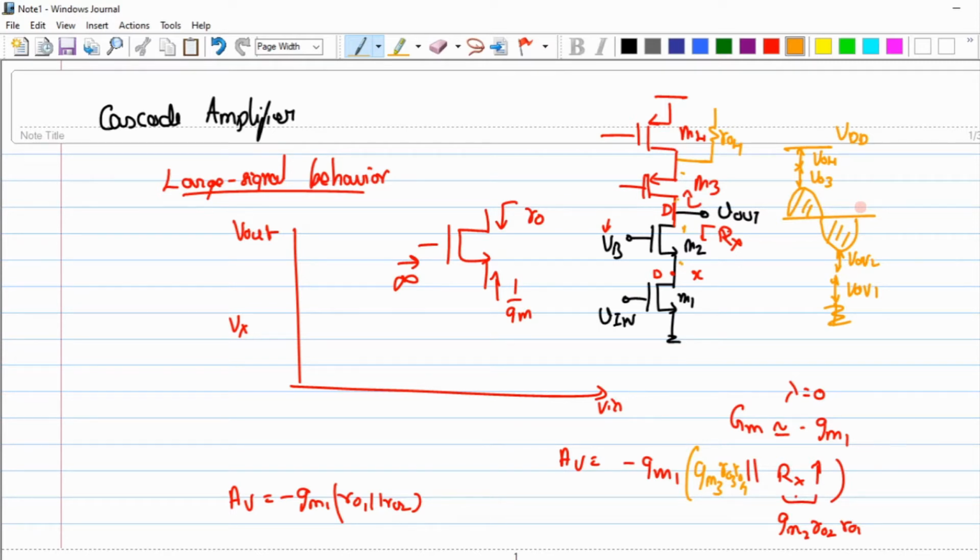Now, for example, if you want to further increase the gain, what can I do? You can just think. However we did it, why can't you think in the same direction? What happens if I stack one more transistor, both across my PMOS structure as well as across my NMOS structure? What happens to the Rout? It boosts up very large, okay?